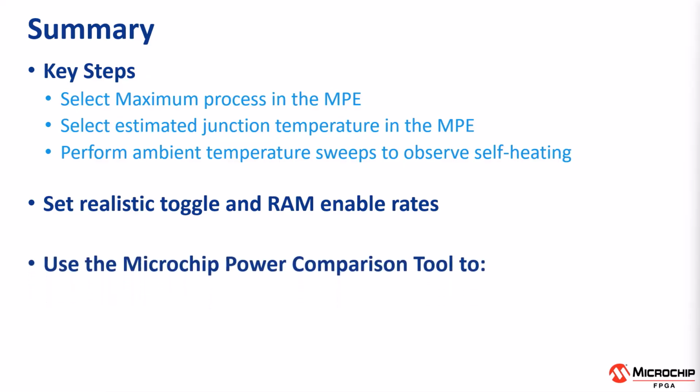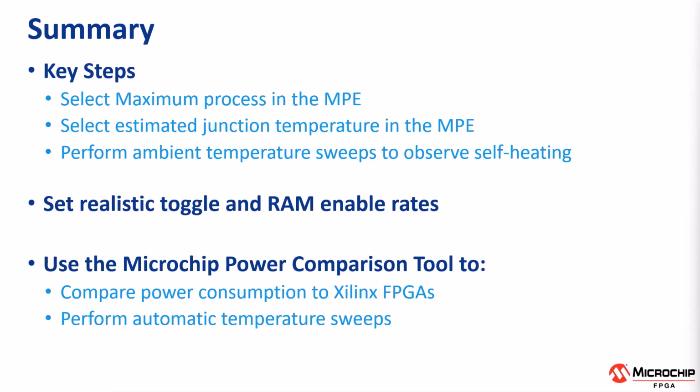I also introduced the Microchip Power Comparison tool that can be used to compare the power consumption between PolarFire FPGAs and Xilinx FPGAs. The tool automatically performs temperature sweeps and provides graphs showing power versus ambient temperature, junction temperature versus ambient temperature, and the device self-heating effects.